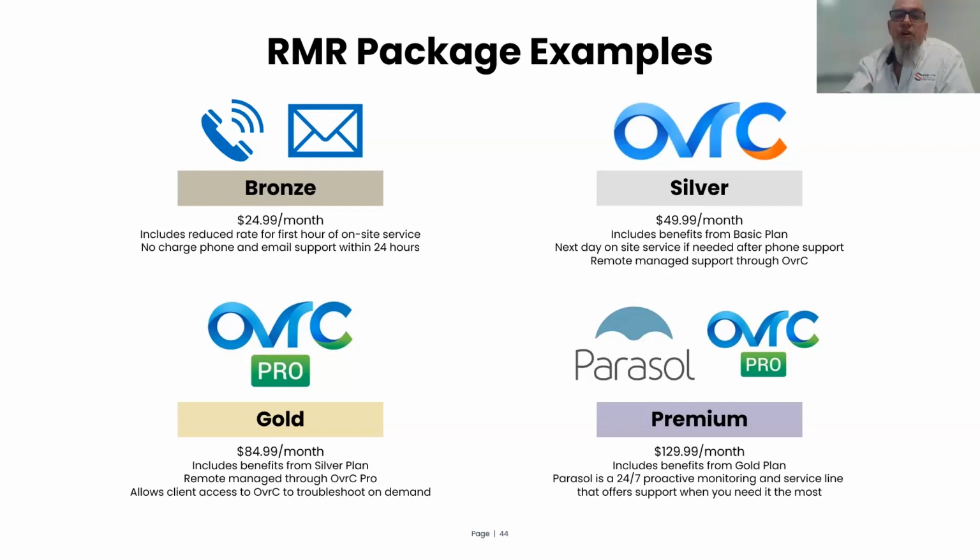I am going to answer one more question that came up because this is one I get asked a lot. Should we be using higher bandwidth cable like Cat 7 or Cat 8? No. The ANSI TIA residential 570D wiring standard calls for category 6A to every device location, plus coax, plus fiber. The reality is N-BASE-T scenarios of 2.5 and 5 gig were developed to be able to use existing infrastructure on 5E and 6 up to 100 meters. 6A gives you 10 gig up to 100 meters.